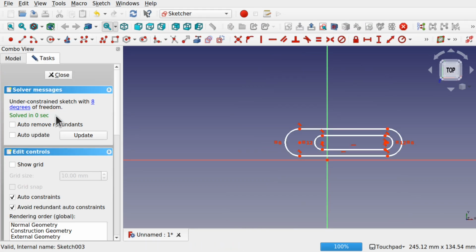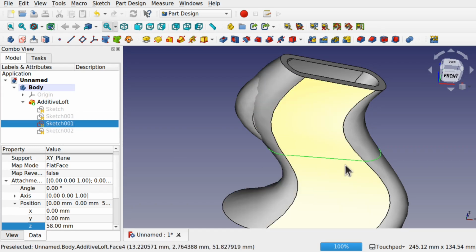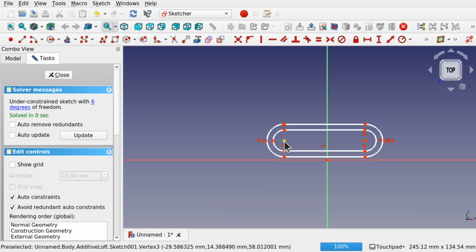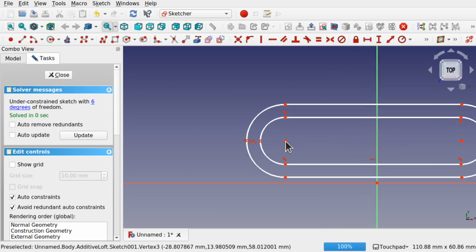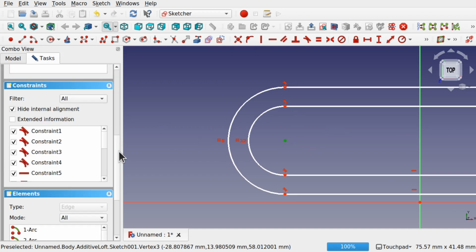and we'll double click sketch 3. You can see where that is, and we're looking for sketch 1, which I'll press the spacebar on just to show it. Double click that, and if we start moving this inwards, we've got this constraint to here, so I'm going to take some of these constraints off. Let's come down to our constraints and have a look, see what we got.